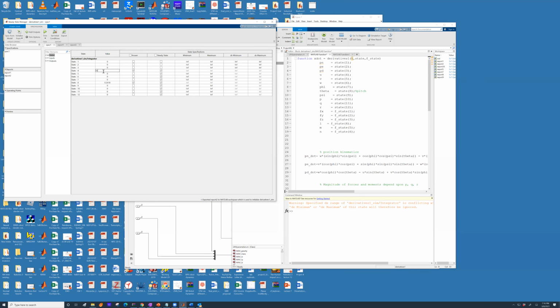depends upon how you want to state it, because your airspeed, if you are going to say airspeed is 10, then you are going to have the forward velocity, which is 10 multiplied by cosine of 15 divided by 180 multiplied by pi. This is going to be your forward velocity, and then your derivative, if you think about your height, that is going to change. But before we change that, let me run this for a second and see what happens.